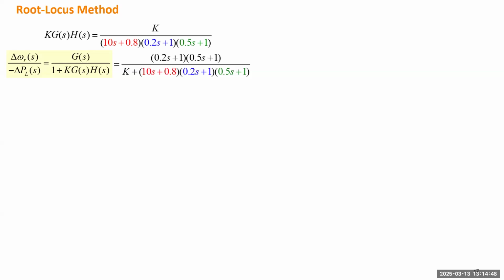So this is the closed loop transfer function. This one will tell you the stability. You have to make sure all the roots of the denominator are on the left-hand side of the imaginary axis. Okay. So when K changes the value, for instance, if K equals 0, the open loop transfer function's poles will be the closed loop transfer function poles.